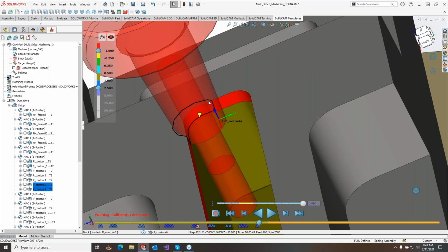So don't expect to always see this nice big black border, but you will always see this toggle, the marker here for the collision point. And obviously there's a collision point here, but as we know, it's colliding along this entire thing. So there is really no specific collision point. There's lots of collisions, but if you can't see the black border, don't be concerned about it. A lot of times collisions are really tiny. You'll see the yellow collision marker and you can use that.